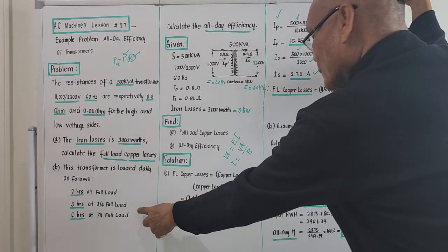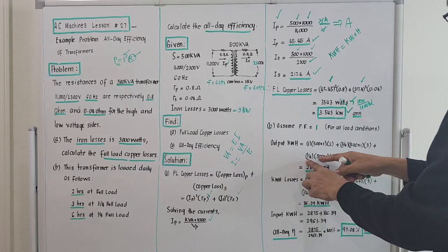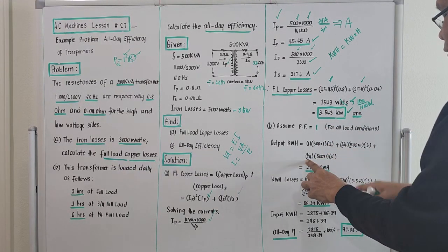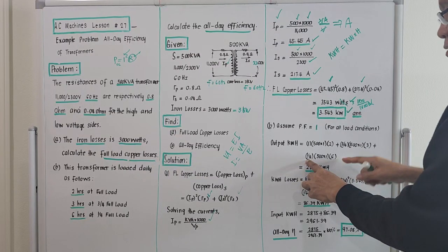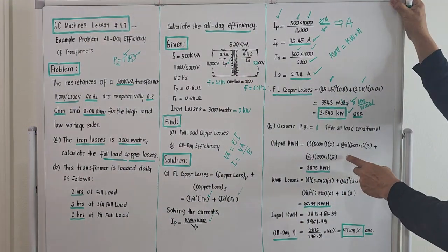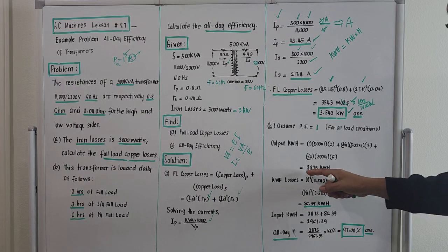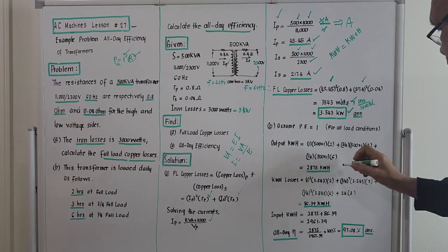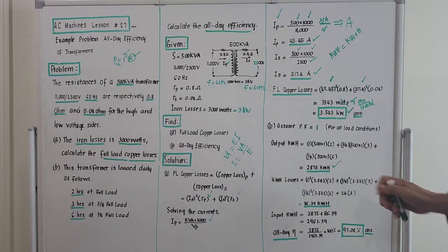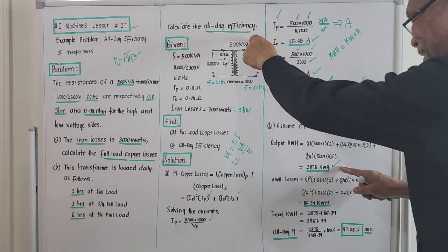It is only 1/4 full load, so there is a multiplier 1/4 here. The true power is 500 times 1, meaning the load at that one is only 1/4 of 500 times 1, multiplied by 6, since it was operated for 6 hours. So this is multiplied by 6. Taking the summation of this using our calculator, it is 2875 kilowatt hour. This is small compared to the rating, because this is 500 kVA, right?